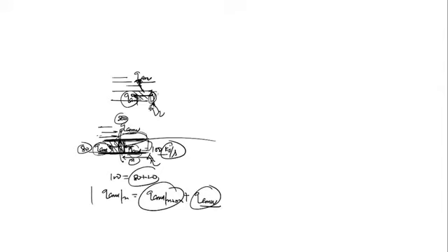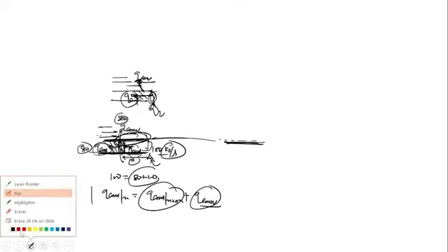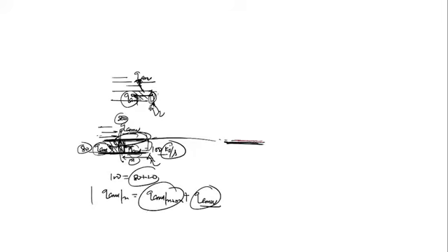I am not talking about this conduction. I am talking about, if I exaggerate this here, this is the pipe wall. Any fluid layer on the surface will be stagnant due to the no slip condition. Any fluid layer on the surface of a solid is stagnant. Yes or no? This is the fluid layer. It is stagnant. So when the fluid layer is stagnant, the heat transfer on the surface is through conduction only.